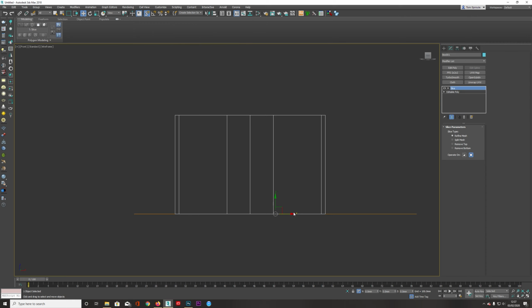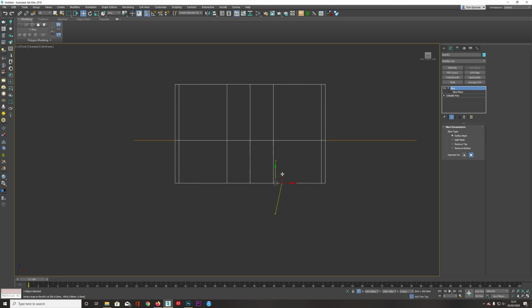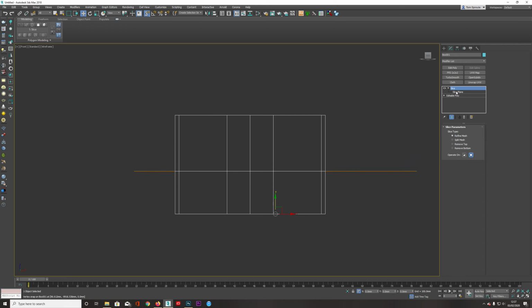And then I'm going to press 1 to go in sub-object mode here. And I've gone into the slice plane here, and this allows me to move this without moving the geometry. If I'm not in sub-object mode, I try and move it, all the geometry moves. So here I'm just moving the slice plane itself. I'm going to undo that movement. I'm going to come up 270. Now this is interesting because that's actually moving on Z-axis, but because we're going front on, it thinks that's Y. So I'm just going to put this 2700.